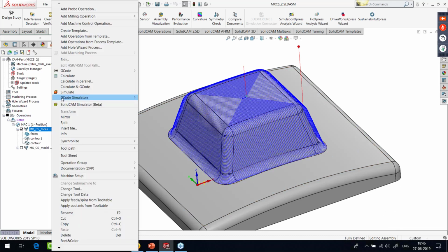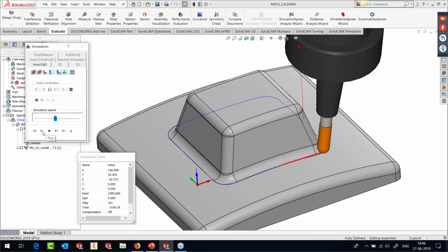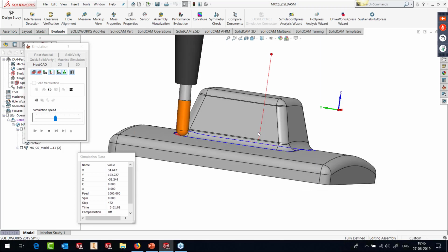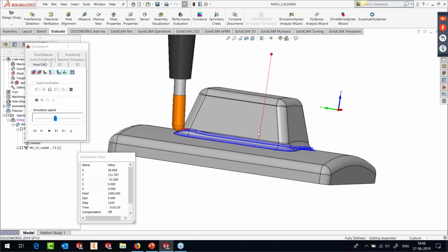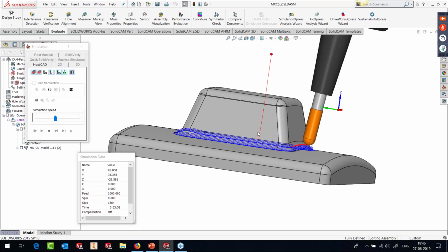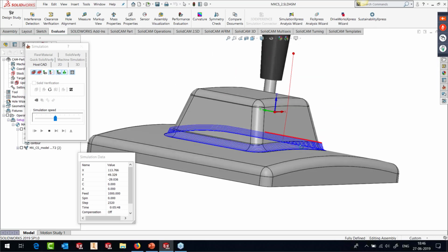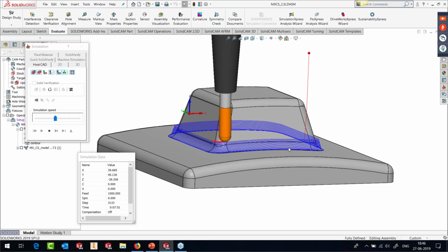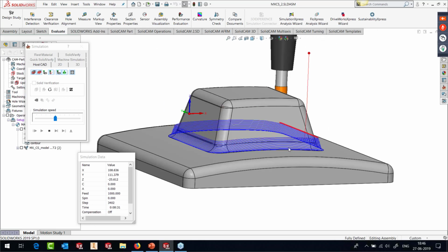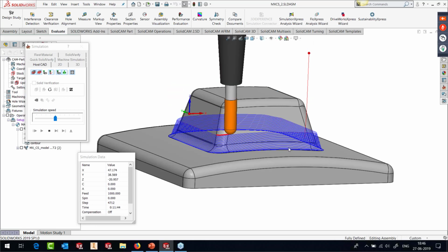So if I run the simulation slowly, you can see that it's using a nice 8 lines that I've defined, and based on those lines, it is now machining the entire group of surfaces that I defined and going parallel to the curve. So it doesn't matter where it is machining, it will always be 0.506 between 2 generated slices. So it will always have constant step over in 5 axes.